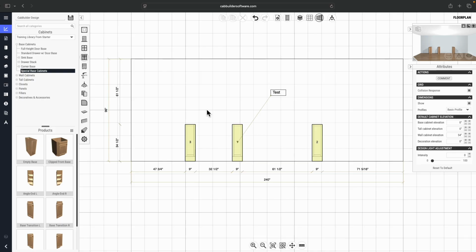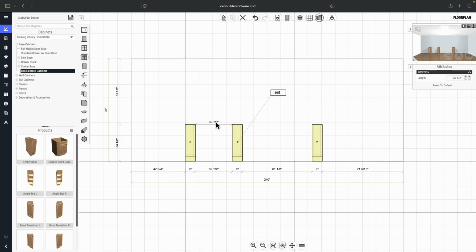Another change in the design module is the ability to place static dimensions. When you use those user dimensions at the bottom, you would typically select 2 different objects, let's say from this endpoint to this endpoint. This then brings up this dimension line that you can then use to move the initial object relative to the anchor.